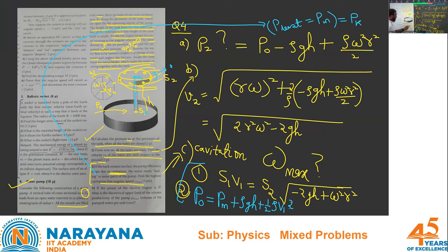That limiting omega or the omega max is the value where the pressure on the axis of the upper constriction becomes Pk. Right? Because that is the least, and saturation vapor pressure will come there first, so cavitation will start from that point. So if I can avoid cavitation there, it will not be present anywhere else.